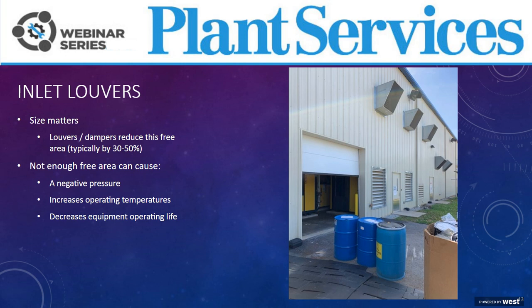Begin by determining what the free area rating is for the device you're installing, so louver, damper, bird screen, etc. Then you have to oversize your opening so that the total free area requirement of the compressor is still met.